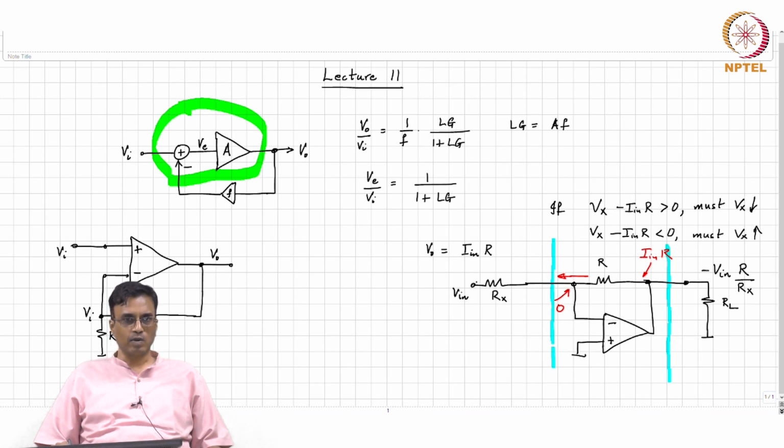All right. So you try to make a current controlled voltage source, and if the current source is bad, then it is equivalent to an inverting amplifier. There is of course another way of deriving this, again from first principles. Okay. So if you want V out to be the negative of V in, what does it mean? V out plus V in must be equal to 0.